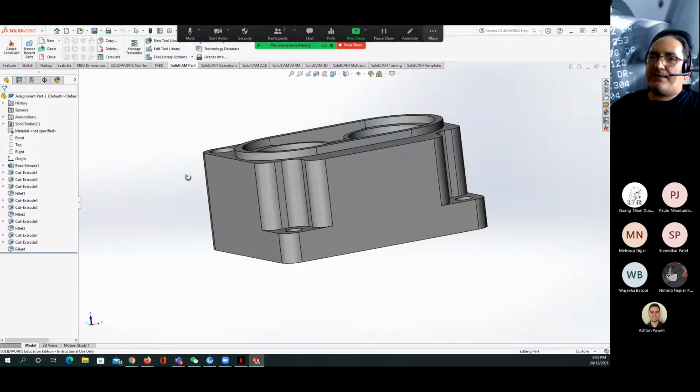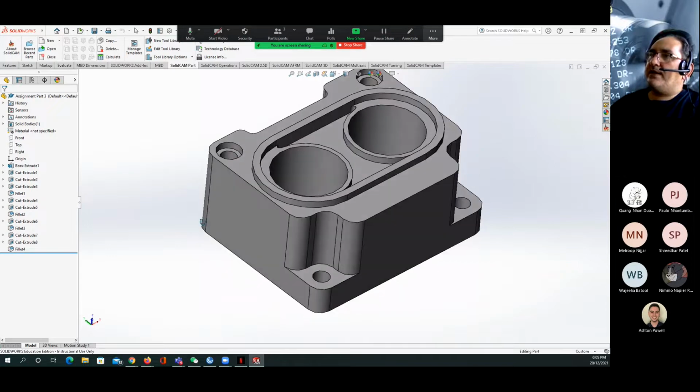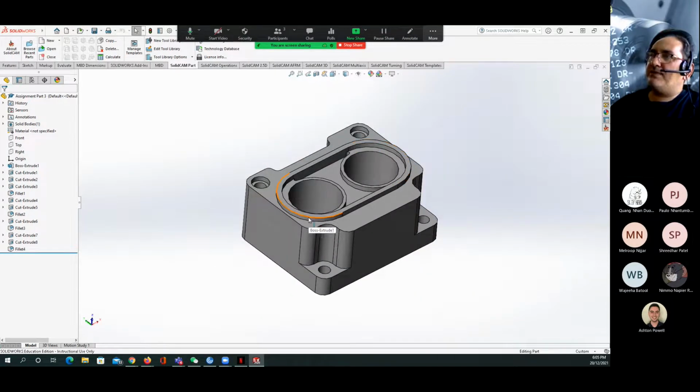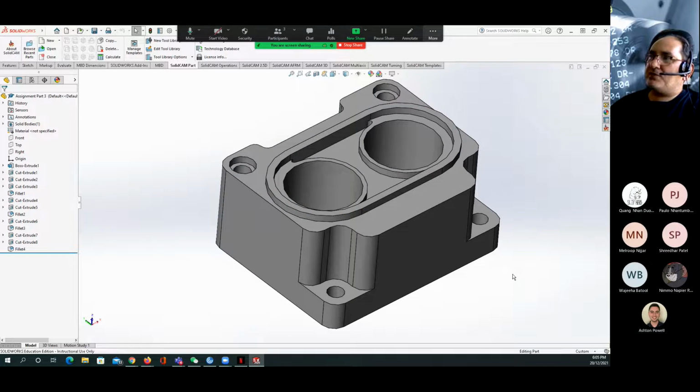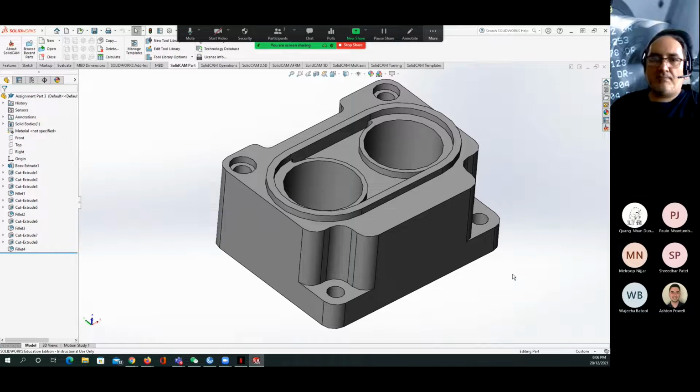Okay, now I made that, and I said, okay, now this can be a good example for my advanced manufacturing students to practice on how to use the CAD CAM. In the CAD CAM, instead of doing the hand sketch, then the tool path and writing down the code, it's much easier to make the CAD model, then choose the tools from the CAM software and do the machining virtually. And then, of course, the code will be listed. We can simply copy it, paste it on the machine, make some modification, and run it.